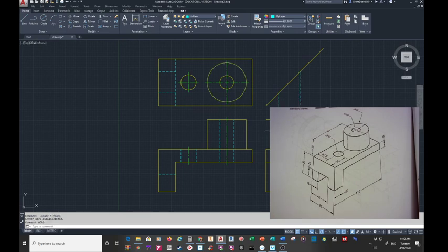Now, oops will work on the last thing that you deleted, even if you are 3 commands or 2 commands or 15 commands later. Oh shoot, I shouldn't have erased that. If you type in oops, guess what? It brings up the last thing that you deleted. So, it works. Alright, I'm going to change this to object, and I'm going to go to line, and I'm going to project this one over and down, and it goes to just right here.